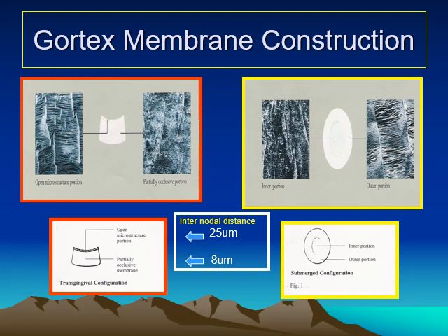The Gore-Tex material is made of expanded polytetrafluoroethylene, which resembles polytetrafluoroethylene. They are chemically identical, differing only in physical structure and strength. Solid polytetrafluoroethylene is non-porous and does not allow cellular ingrowth or attachment. In contrast, the microstructure of expanded polytetrafluoroethylene can be adjusted to permit cellular infiltration and collagen penetration. It consists of solid nodes interconnected by fine, highly oriented fibers, forming a unique porous structure, as we see. The material is neither woven nor knitted; consequently, expanded polytetrafluoroethylene does not fray when it is trimmed and it is not abrasive.